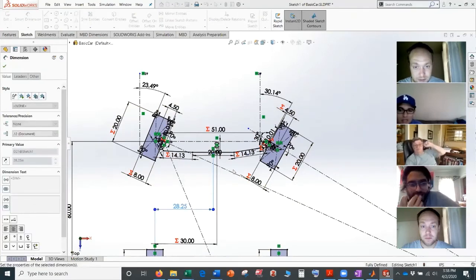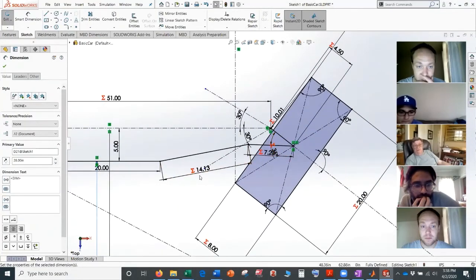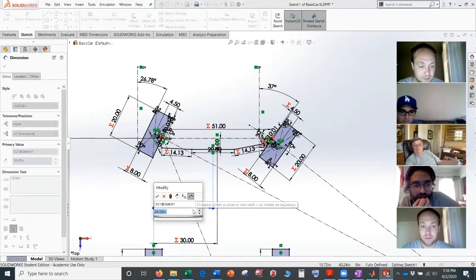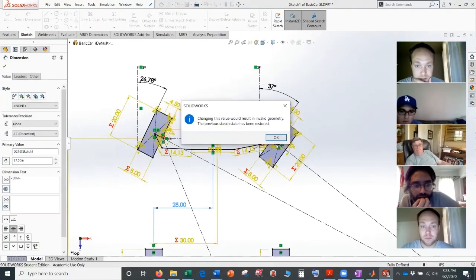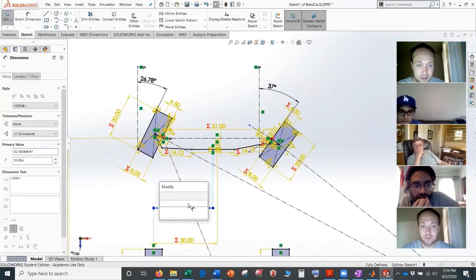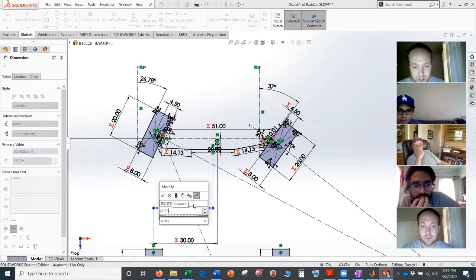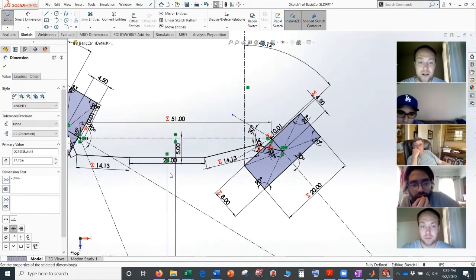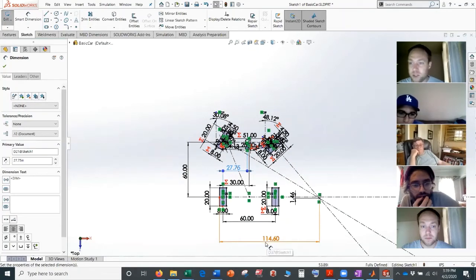Well, Chris, our approach was we're going to move the rack closer to the center line of the wheel. I think that's good. And so it's then almost straight, and then decrease that 30 degrees down to about 22. Once this gets straight, that's going over center basically. Right now we're about to go over center on that wheel, but we got a nice turning radius here, 114. And the rack distance is like 2 inches max, at least for Bajas? Baja does about 2, but there's no rule on that.